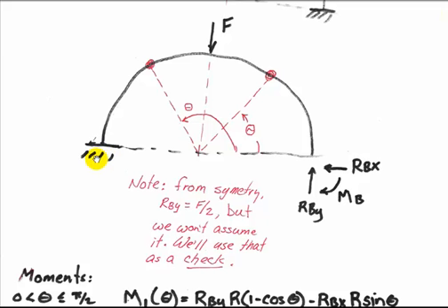Because of the direction that I'm going to be integrating things, I'm going to be starting things at this right hand end and integrating around the circle and stopping when I get to the left hand end. I don't actually have to do any statics here. So what I have to do with these redundant loads is write energy terms caused by these loads to give me the deflection at this point caused by each of these loads.